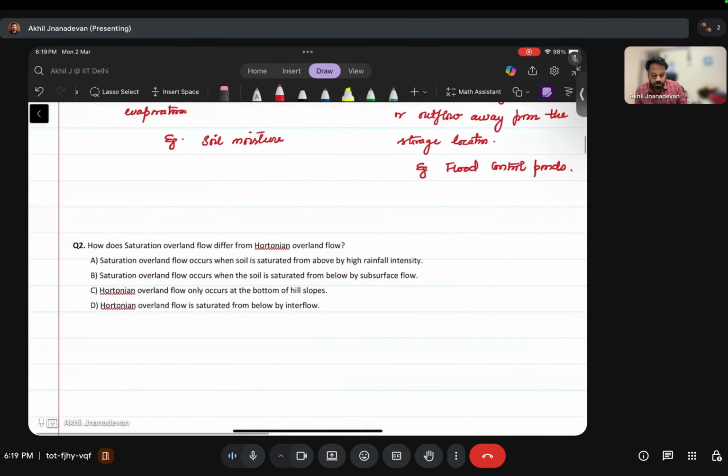If I want to show you the structure of this tank, this will be our ground level and this particular area was getting flooded. We will direct the flooding water to this tank and the tank gets filled up. There will be an outlet at the bottom of the tank that releases the water at a rate Q, which will be a very slow rate.